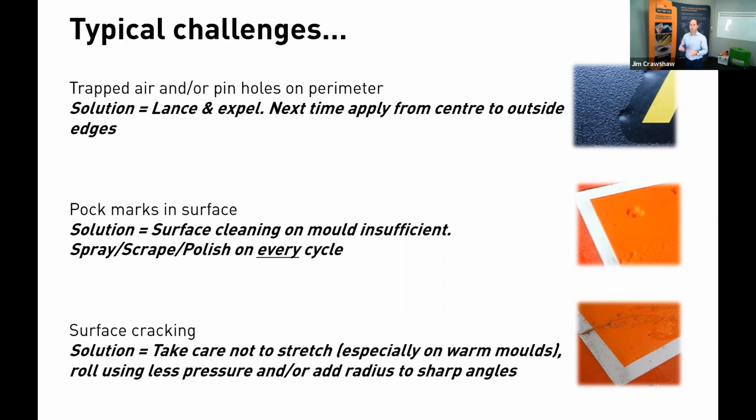So there's some residue left on the mold, whether it be adhesive or some other foreign material. So our solution there is cleaning every cycle. So just make sure you're spraying the mold, scraping off that residue and polishing it on every cycle. So I'll show that in our live demonstration as well.